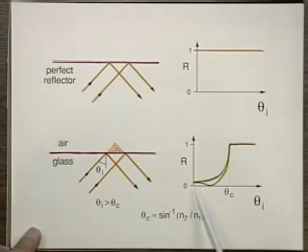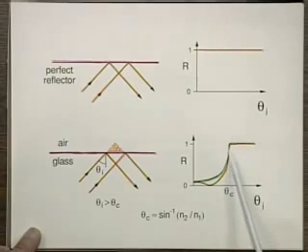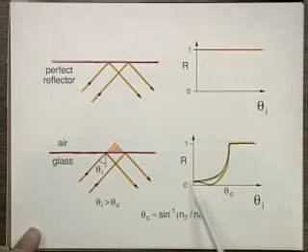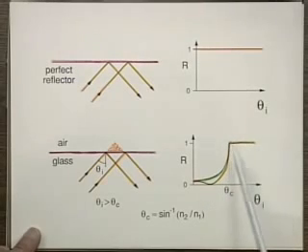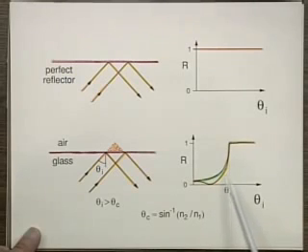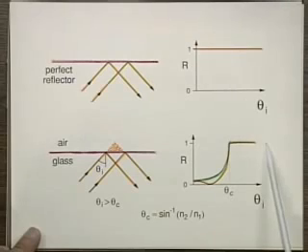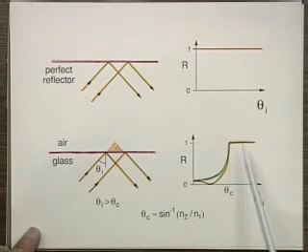But right now we're not going to get involved with polarization. Basically, between glass and air, it starts at like 4%, and for one polarization goes through 0, which is the Brewster angle, and then rises at theta critical to 100%. And for the other polarization, it doesn't quite go to 0, but still rises and goes to 100% at theta critical. So it doesn't matter which polarization, both will go to 100% for theta critical and beyond. And that's what we take advantage of in fibers.